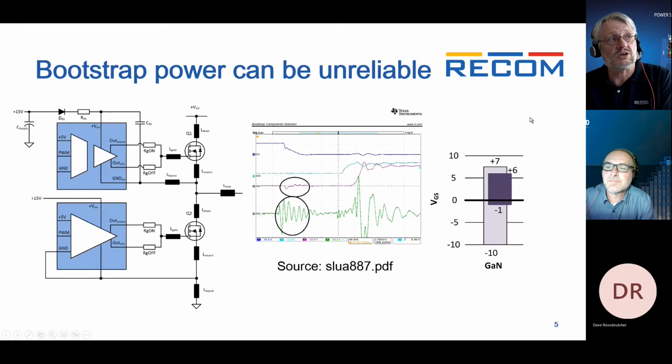Here you can see a circuit based on this design, which I used from a TI data sheet, and you can see here these ringing and output variations in the voltage. That's caused by the fact that you're switching at such high frequencies, and the parasitics start to affect the voltage because the diode reverse recovery time is too slow, and these variations can easily destroy the gate driver. Yeah, very interesting.